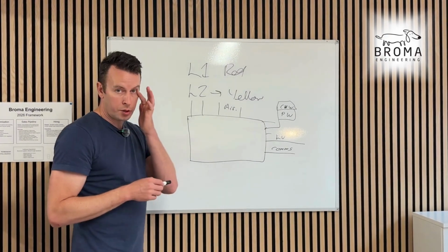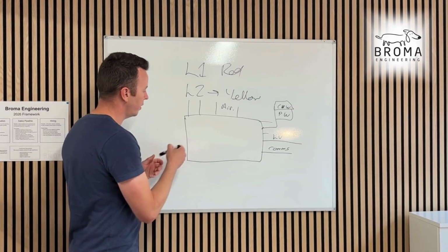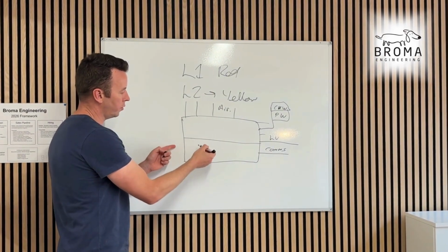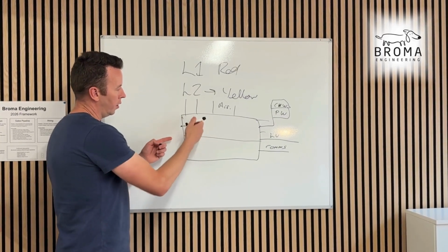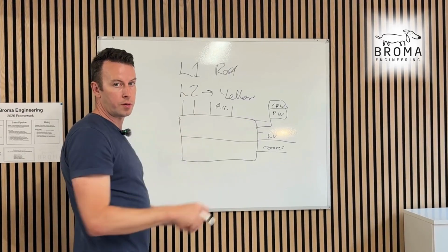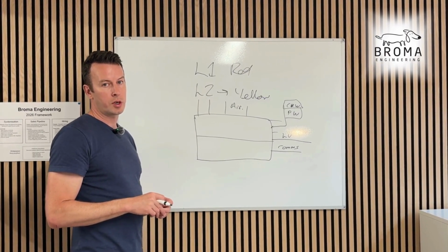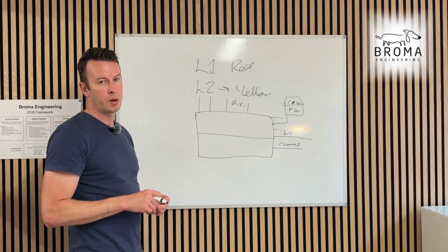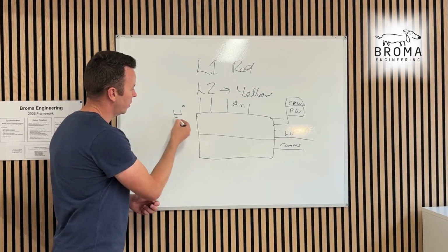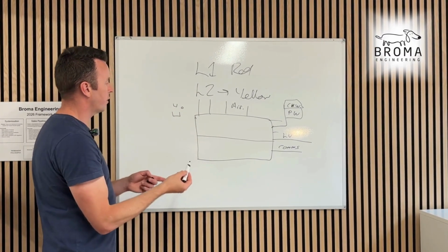And this is where sequencing becomes really important. First of all, if you're rolling something that's very tall, so there's 2 AHUs and 2 sections on top of each other, so it's a 2-story AHU. The containment or pipes need to be out of the way as you roll that down that room. So from a scheduling point of view and from a design point of view, you need to account for that. So you could have them, pipes and cable tray off to one side and comms basket, and you can roll it down, or else you need to leave it down and put it in after.